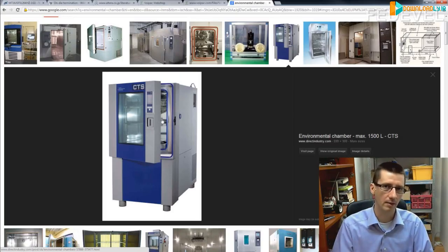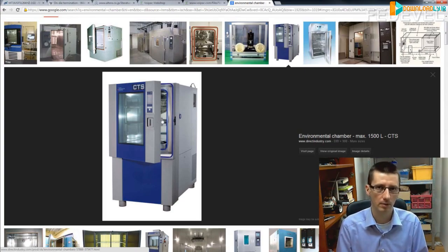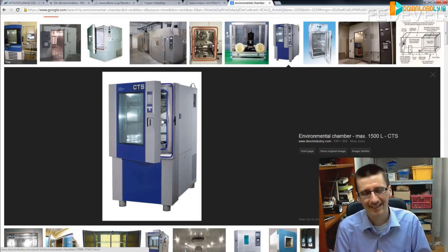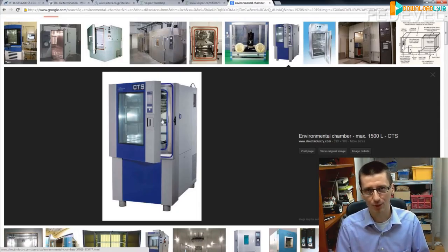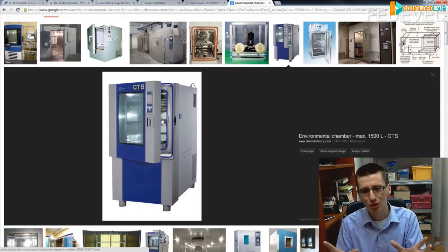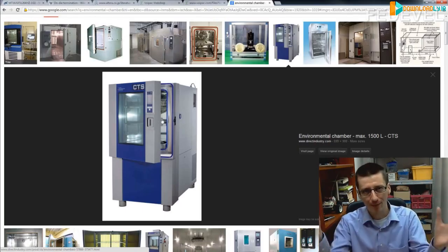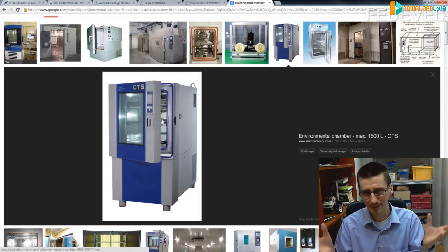It failed again, and you can't debug the board in the chamber, or you can, but it's difficult because, for example, when the chamber is running at -40, you should not open the door at -40, or you can open it, but what will happen then is there will be snow everywhere in the chamber. It will start melting.